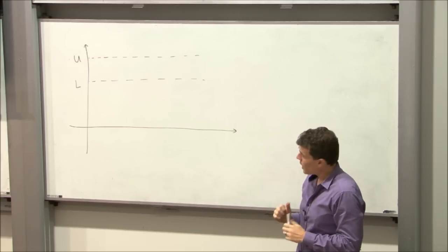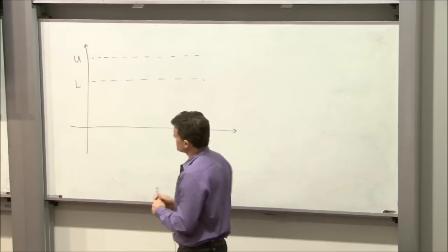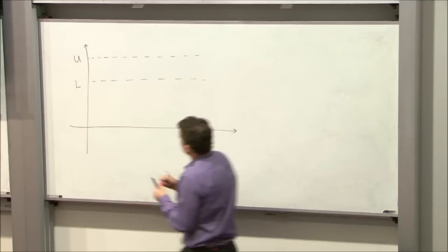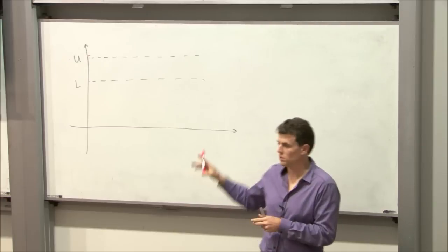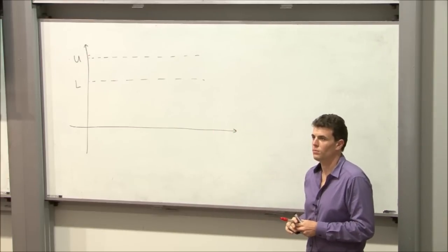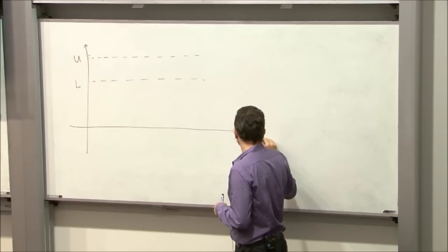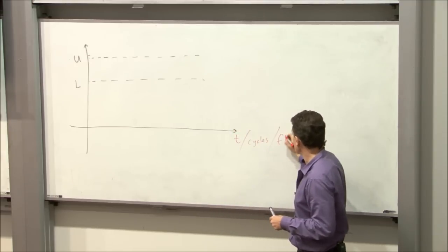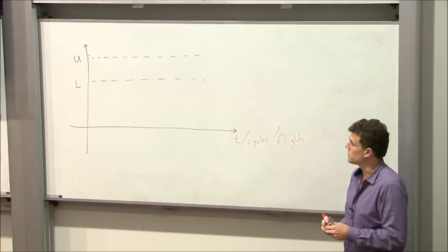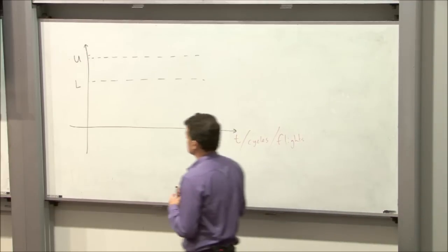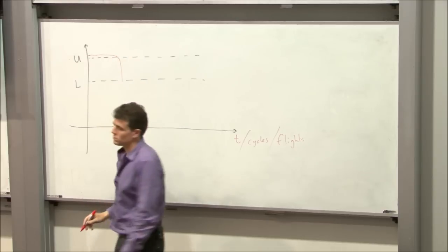Now, that means that everything that we put onto the airframe when it's new has a load capacity that's up here somewhere. It's above the ultimate load. So it won't fail until it gets up there. Now, if we put on this axis time or number of cycles or number of flights or any sort of time-based axis, some things as you load them up will do this.